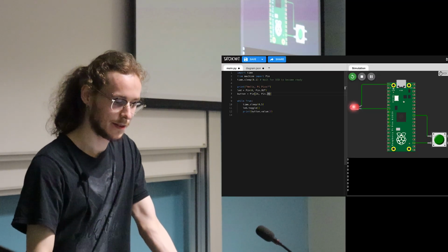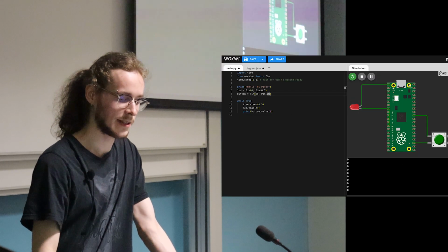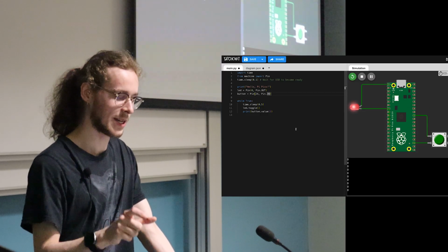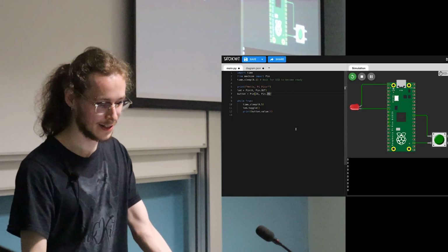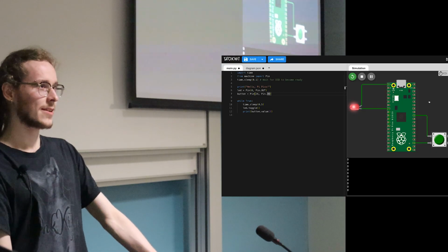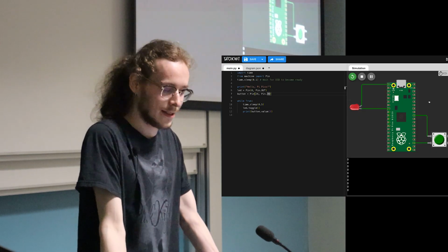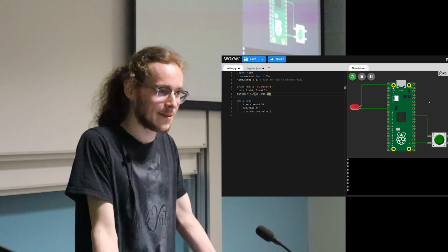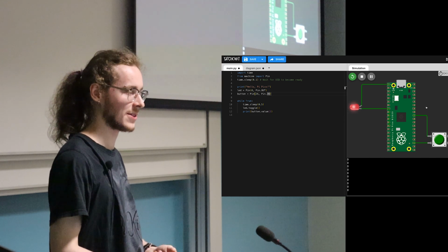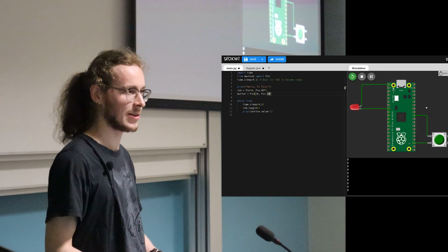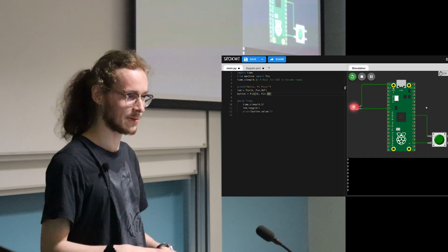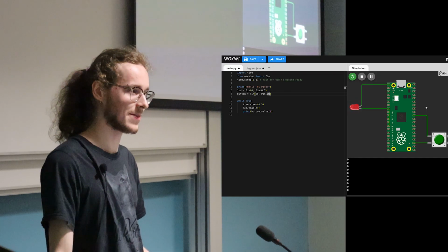And the Raspberry Pi Pico has this functionality in its internal circuitry, which you can just use by adding a little bit of code. For the sake of understanding it better, and I did this myself, I recommend that you read about pull up and pull down resistors, and try and create one yourself. It's really simple to do, but it's a little unintuitive.